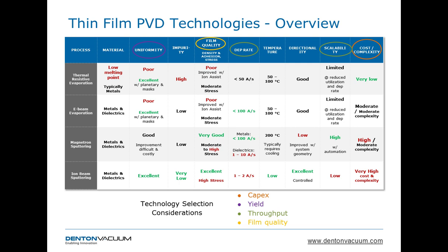If we need something, say for such a high power laser, some key properties that are a more dense film, or for example, better adhesion, ability to withstand higher currents, we would go with a little bit higher cost options such as magnetron sputtering or even ion beam sputtering, which though is very, very expensive and complex.